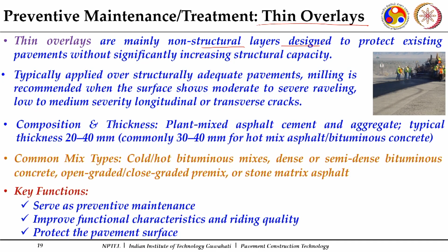So, they will not add to your structural strength, but they can help you preserve your pavement structure. Thin overlays are mainly non-structural layers designed to protect existing pavements without significantly increasing structural capacity. To a certain extent it is helpful, but it should not be considered as a structural overlay.